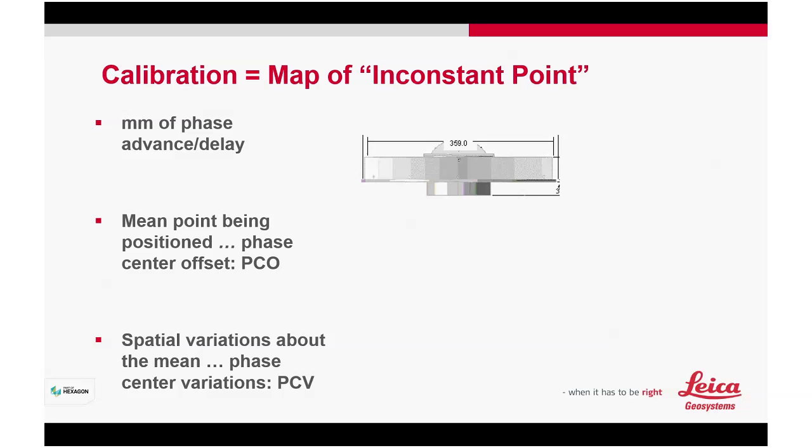variations. Okay, and how good your phase center is, because as you know, the satellite will be moving, up and down, forward, down, whatever, and up again. So the elevation will really affect your phase center. If your phase center is no good, you can imagine the phase center is really moving. Okay, this phase center offset is talking about the contact point, the physical contact point to the phase center.